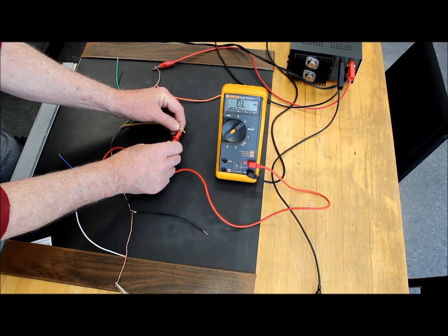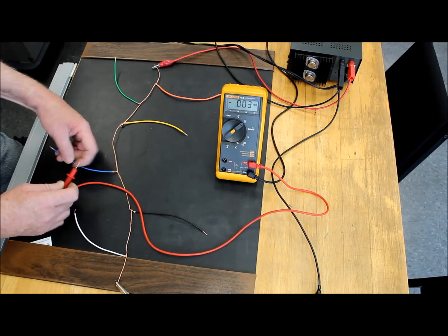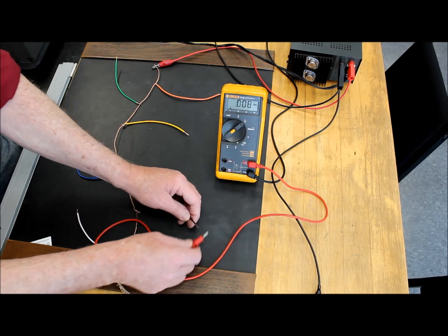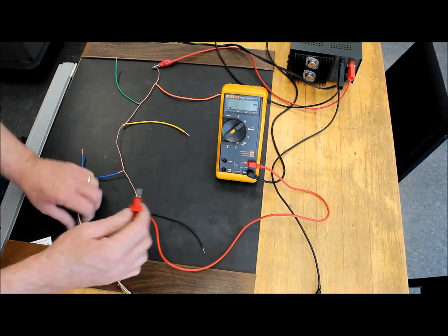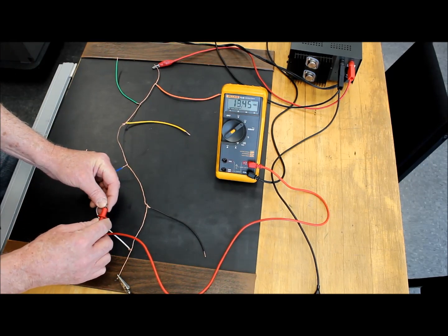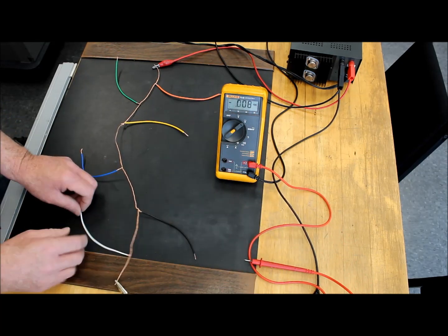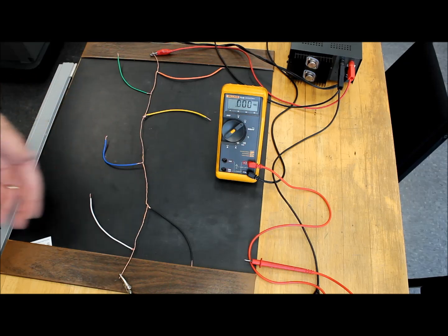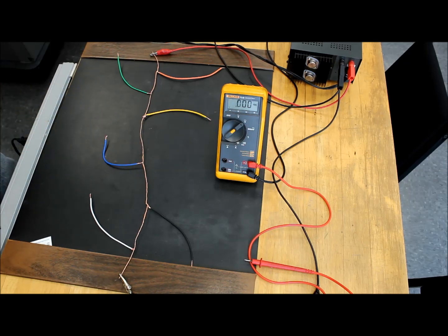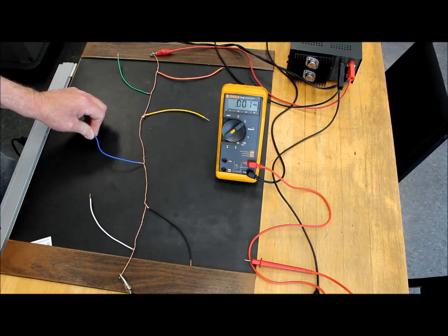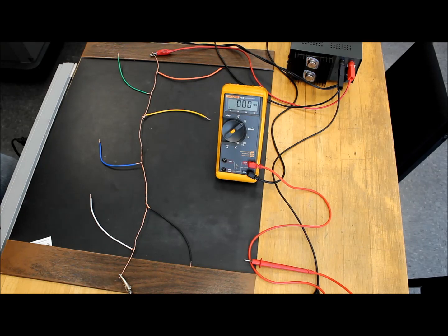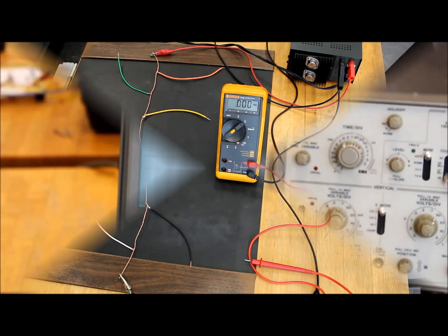Third one, same voltage. Fourth one here, same voltage. Fifth and sixth. So what you're seeing is that voltage put on the bus, in this case just a steady 13.5 volts, is available to every node attached to that bus. In this case I have 6 of them, and they would represent 6 different computers or modules.